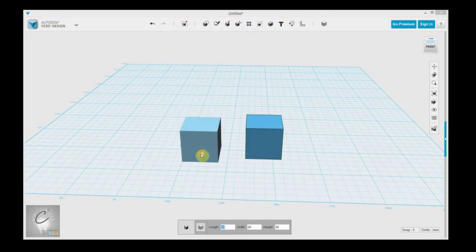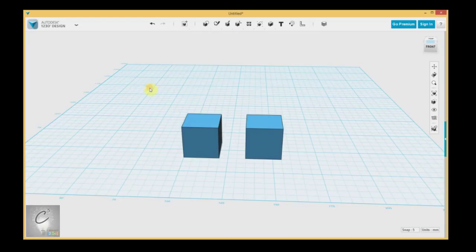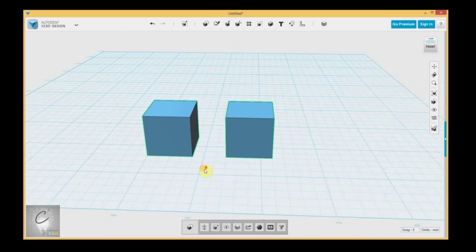If you have two objects, you can left click and then drag. You create that selection marquee, and it's going to select all the objects. Now with the selection marquee, you don't have to fully enclose the object to select it. I did that there, but it'll select anything that it barely touches. You can see I'm going to select both cubes, but I'm not going to wrap around both of them. You'll see both cubes got selected there.